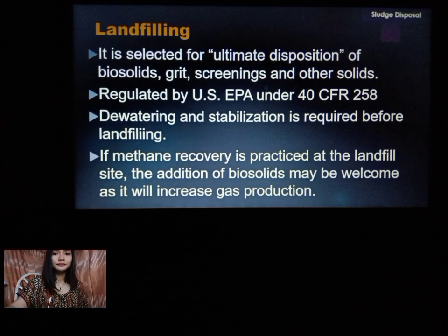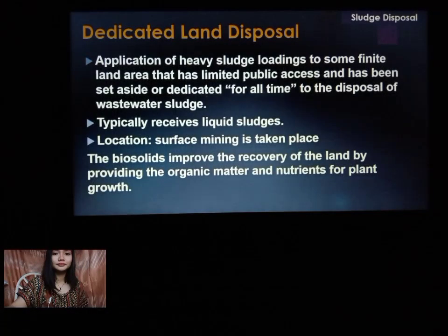and other solids. Landfilling of biosolids in a sanitary landfill with the municipal solid waste is regulated by the United States Environmental Protection Agency under 40 CFR 258. The dewatering and stabilization is required before the landfilling. If methane recovery is practiced at the landfill site, the addition of biosolids may be welcome as it will increase the gas production. Next is the dedicated land disposal.